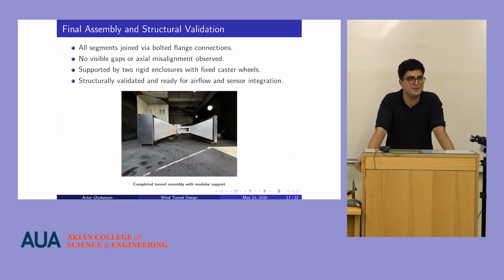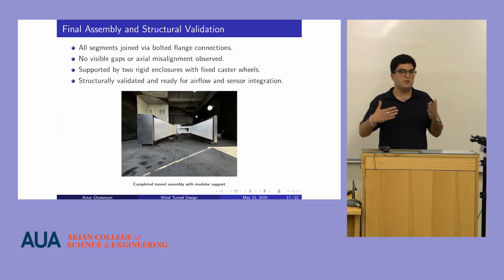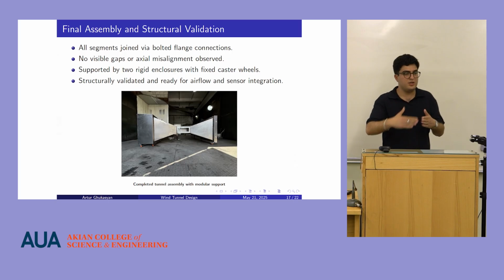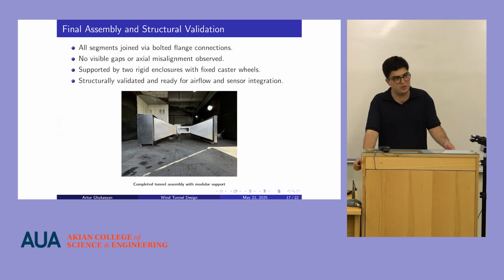Essentially, I think the material selection has been changed 3 or 4 times. At the beginning, we tried to build something that is not as heavy, so it's easily transportable even without wheels. Initially, some types of wood were considered, but wood has other problems with bending and brittleness. Also, construction-wise, having 2 woods connected at a certain angle in a vacuum is quite hard to accomplish. That's why we moved initially to aluminum sheets.